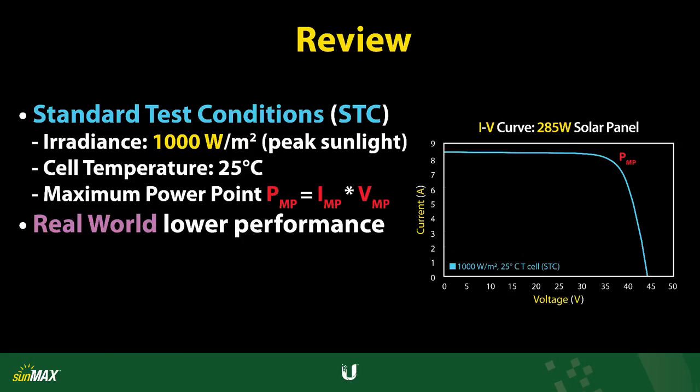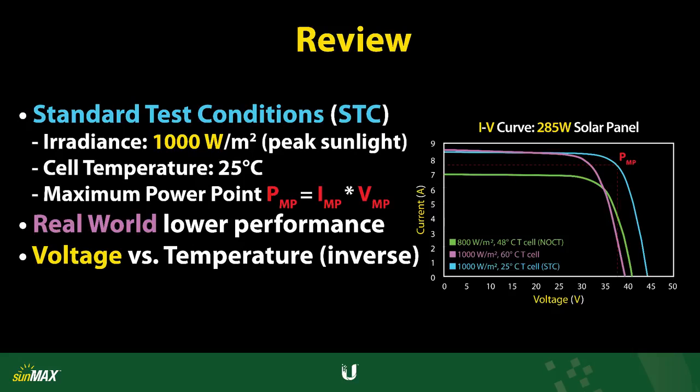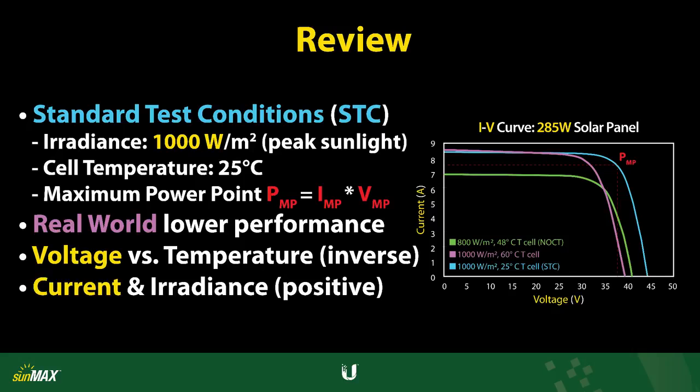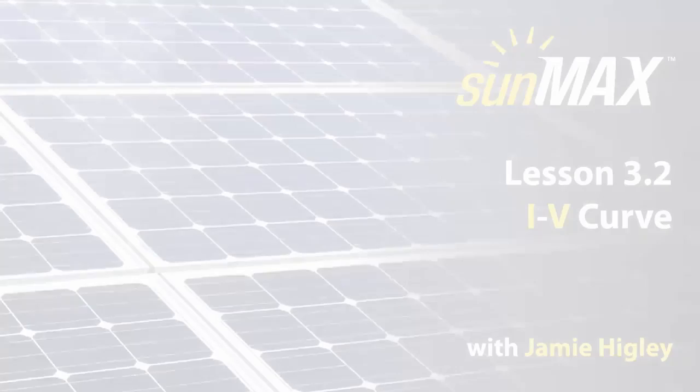Real-world performance varies from STC, since irradiance and temperature ratings are subject to location, as shown by the nominal operating cell temperature and demonstrated in the real world. Voltage and temperature are inversely related, while current and irradiance are positively related.